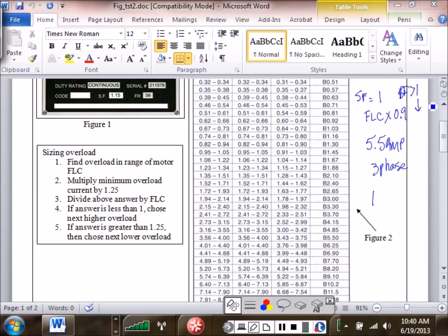Because most of your industrial motors are going to have that. The motor is either rated as continuous duty or intermittent duty. So a motor that's rated for intermittent duty is going to have less copper in it, right? Because it's not designed to run all the time. If you've got an air compressor at home, it's going to be an intermittent duty motor, right? Because air compressor motors don't run all the time. So they can put extra copper in it and get a lot of extra horsepower out of it, but they only do it for what?